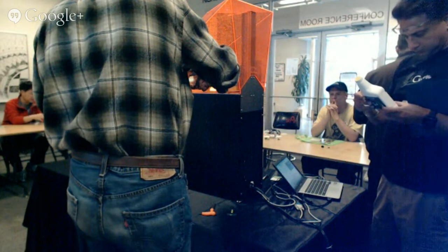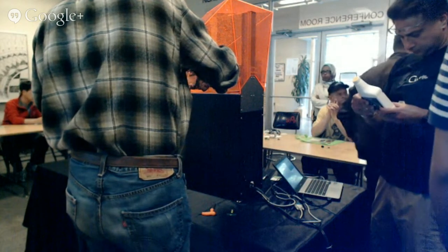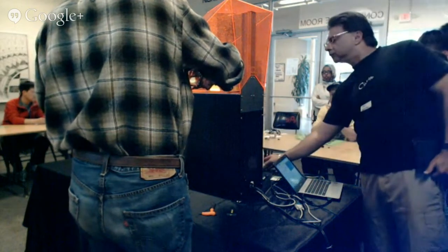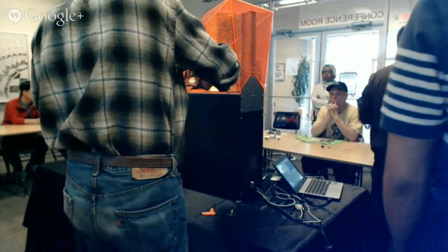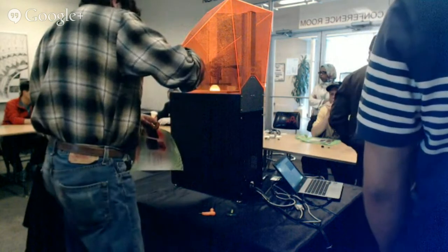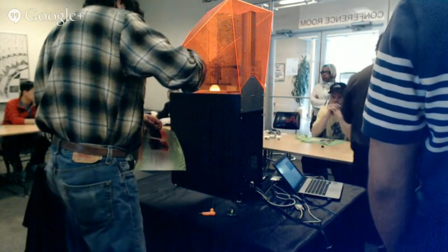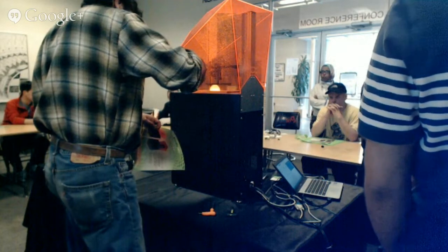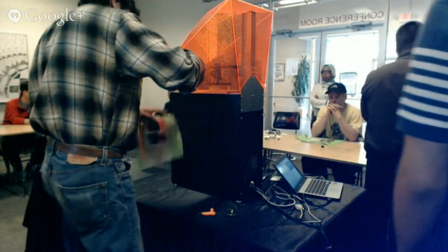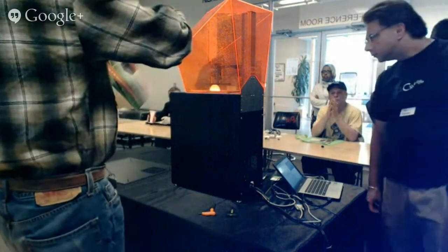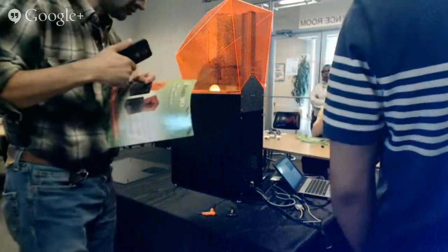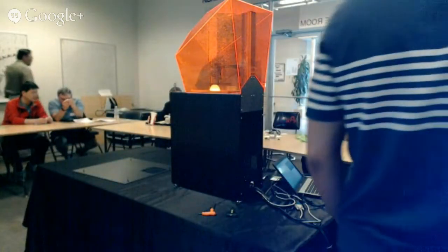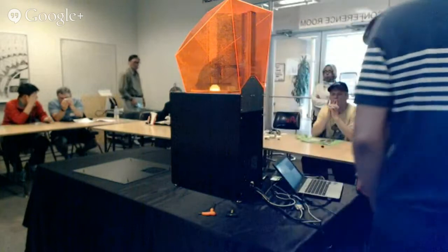So anyway, the projector is exposing the resin. That's right. All right, so it pulls all the way out of the resin. What you want, you need to pull high enough that the surface area of the part completely releases. That way, the amount of new resin flowing in under the part is uniform, right? If you look at the way that lifting works here, you have to watch this carefully, right? You'll notice that the vat is only secured at one end. The other end is free.